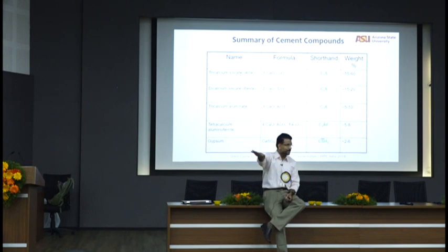In the US, nobody does that. They have just one clinker. They don't even touch or mess with their chemical composition. There's only one cement. If you want a high early strength cement, what do you do? Just grind it finer. That's it. So grinding. So they don't play with the chemical composition at all. Every cement that comes in, except high alumina and low alumina cements, because there you have to add alumina, you can't do anything else. But with strength, from a point of view of strength, you control the strength completely by particle size distribution, completely by the grinding process. The advantage?